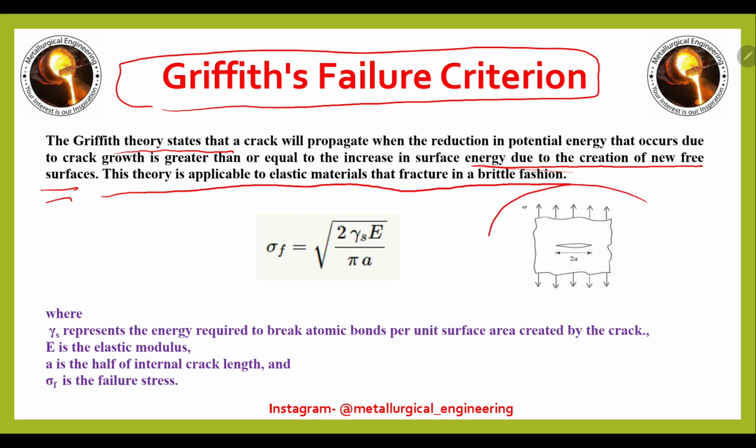Here you can see you have an infinite plate, and if you have a center crack of length 2a, the formula is written as sigma f is equal to square root of 2 times the surface energy term and E, the elastic modulus, divided by pi a. A is half of the internal crack length. This is the important thing: A is half of the crack length.